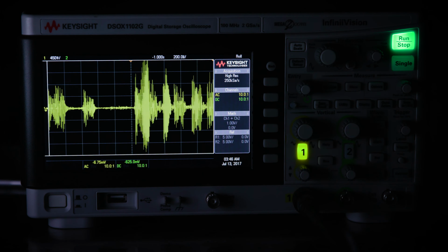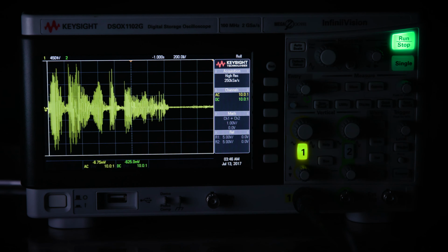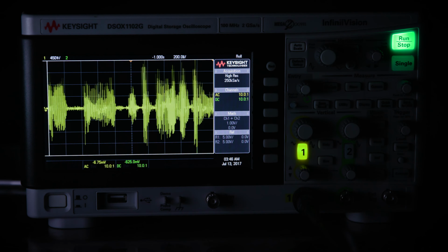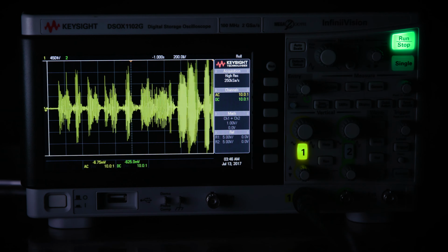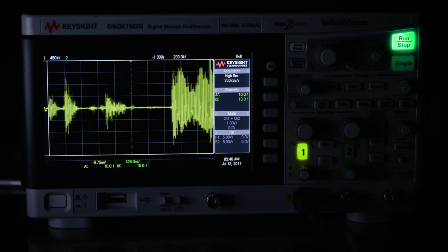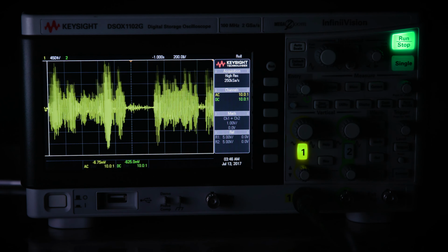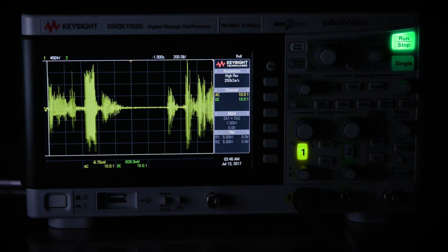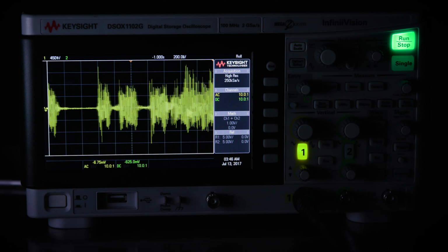One, you're taking the samples at the same time, and two, you're not increasing your bandwidth. If your A to D converter has enough bandwidth to sample the system you want, then you can just offset the clock in one versus the other, take the samples odd, even, and you end up with double the sample rate. But you haven't increased the bandwidth of the A to D converter.